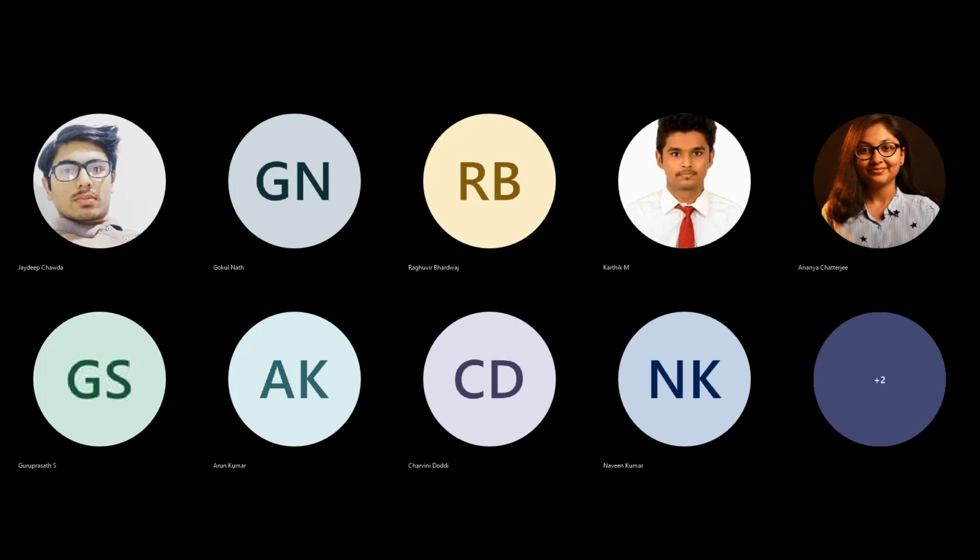Even in a distillation column, to estimate the number of stages, you might have used two different methods. One is the Ponchon-Savarit method, another is the McCabe-Thiele method. In the McCabe-Thiele method, you can easily calculate the number of stages up to 90% purity. At 90 to 95%, the operating line and equilibrium line will be very close.